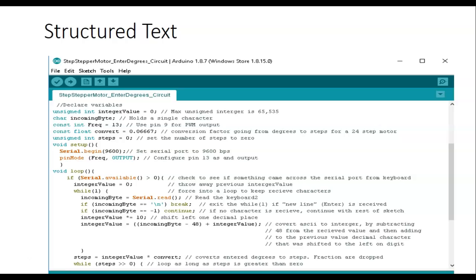Computers don't like that. With computers, your syntax has to be perfect. If your syntax is not perfect, then it's going to translate it into the wrong machine code, or not even work at all. So one of the first things we'll learn is syntax errors, but you can still have problems. You've got to learn syntax, you've got to learn the layouts, you've got to learn the commands. Each one of these off-color ones is a command. But this is structured text. If I'd come up through C, C++, Java, those types of text-based languages, I'd have fallen right into this, and I would be able to learn this a lot faster because this is what I'm used to.